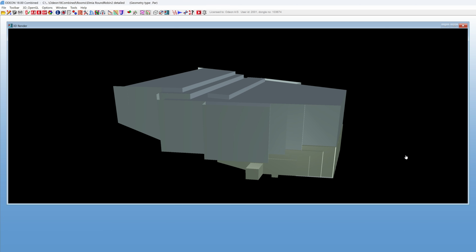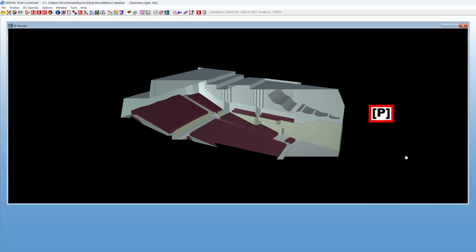You can also make a cross-section of your room, which is more intuitive while in the outer view. You can move the cross-section plane into the model with the P key. Depending on the angle, you may need to hit P several times or hold it for a few moments before you start to see the cross-section. You can move the plane back with Shift P.